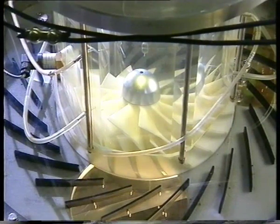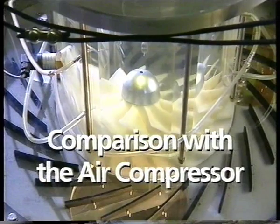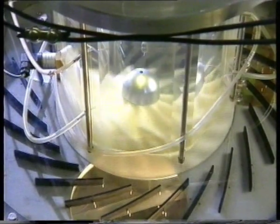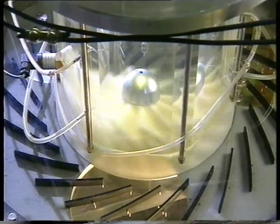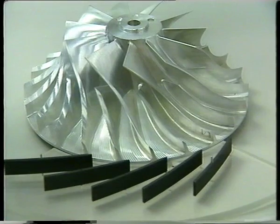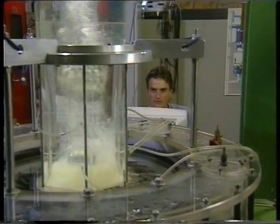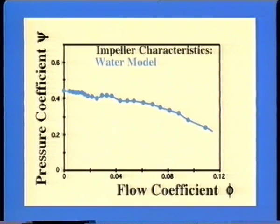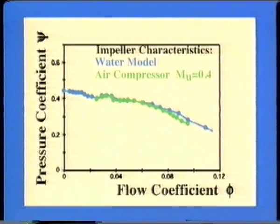The performance map is a good criterion for the hydrodynamic equivalence of the air compressor and its water model. The comparison is made with the air compressor operating at a rim Mach number of 0.2. In particular, the comparison shows that there's an excellent match between the impeller characteristics of the water model and the air compressor.